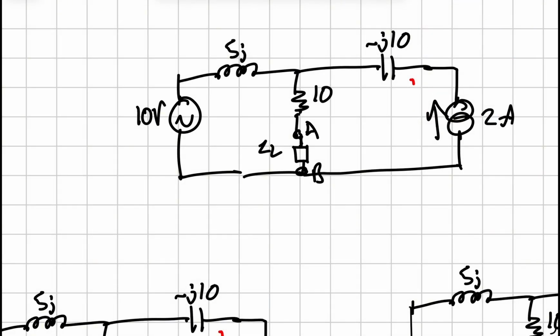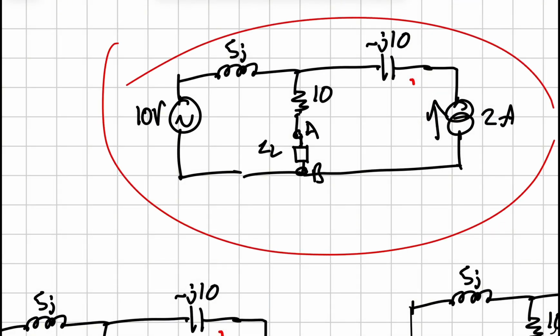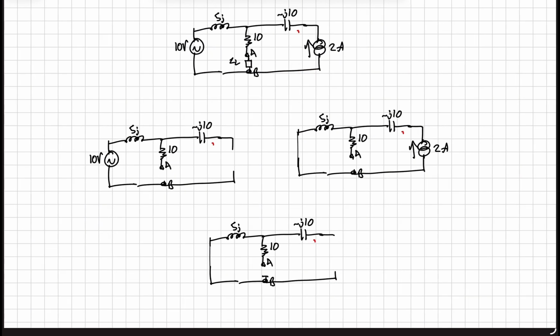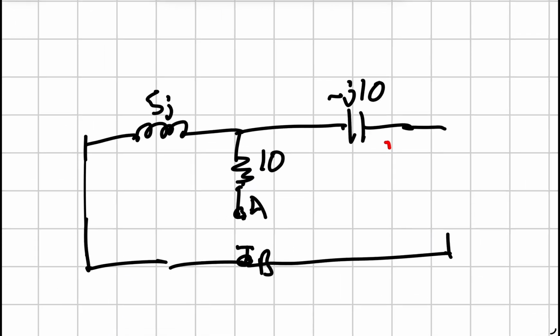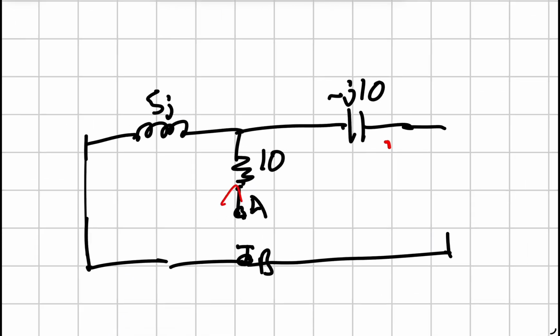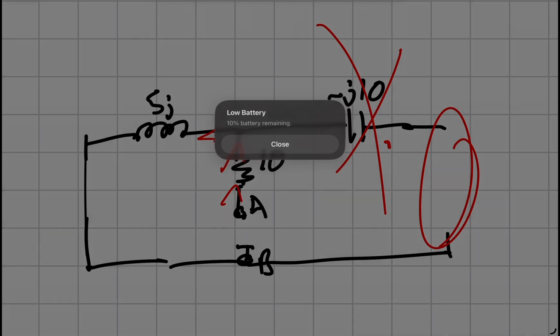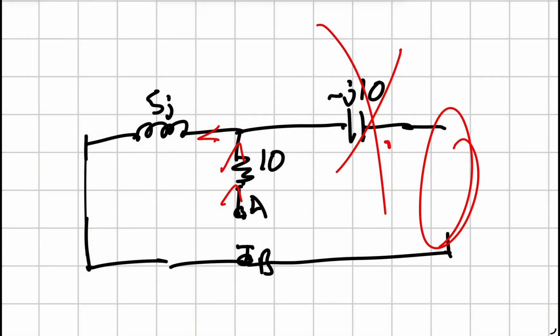So we're going to try another example with an inductor and a capacitor. I've taken the time to split it all already, so it'll be quicker. So I'm going to do the Thevenin's resistance first. You imagine the current's going through here, but then realise that there's an open branch here, so you get rid of that. And then it will go from 10 to 5j. And so it would be 10 plus 5j. That's your Thevenin's resistance.